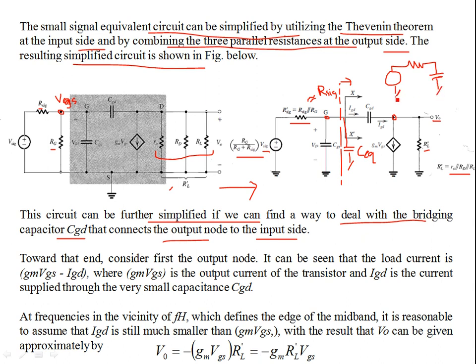So we can write the transfer function in the form of a constant over 1 plus S over omega. This omega is also related to the time constant of the circuit in terms of the equivalent RC, where omega is 1 over R C equivalent. So this takes the low pass form, and we know the transfer function of this circuit. This is the resistance, and then we can combine C equivalent with CGS to form a single pole RC circuit.